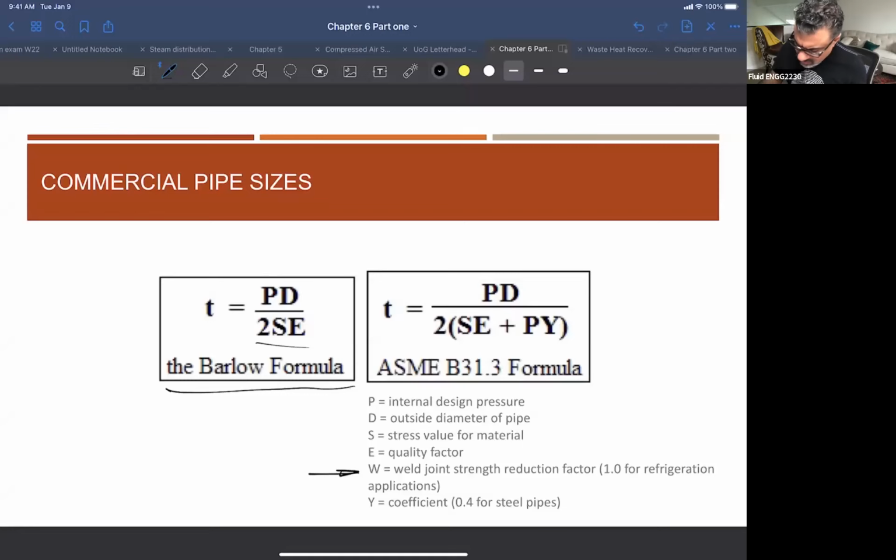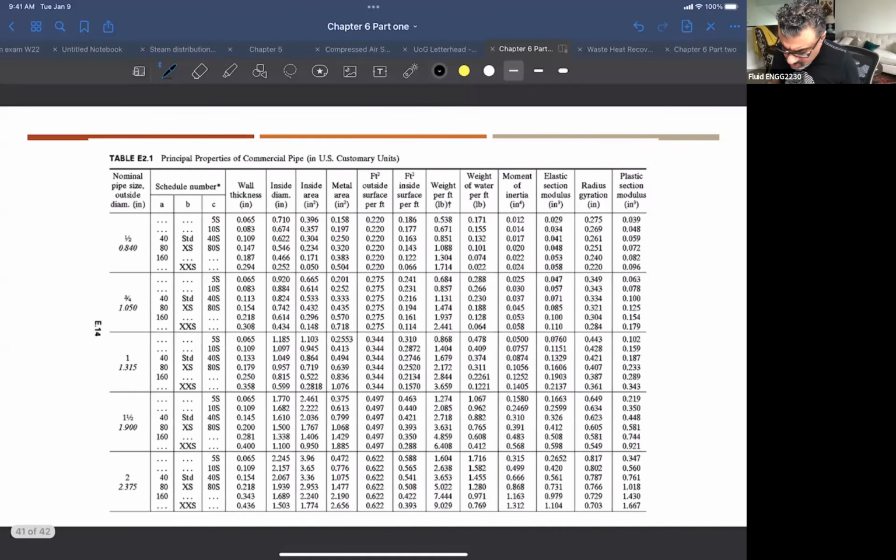Okay, so this is additional design or practical value for when you are really selecting a pipeline in a system. So you will add a little bit of design and mechanics to the fluid mechanics part in order to come up with a final design for this pipeline. So you will see this is just one sheet out of the ASME B31.3.